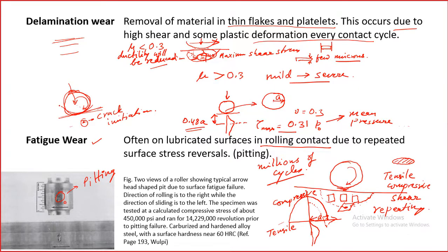And how we can reduce it is by first having the two surfaces of very high yield strength or hardness, we can say. Yield strength should be high. Another important thing is toughness should be high. And another is, you might have heard about clean steel.